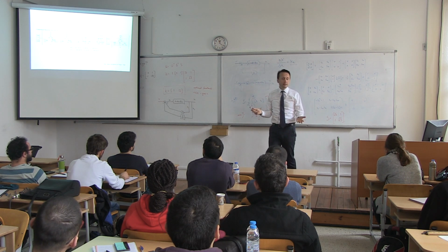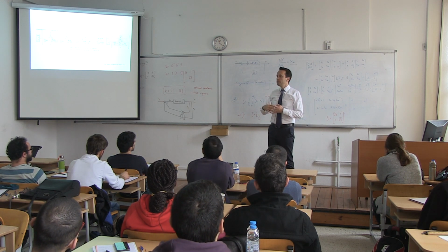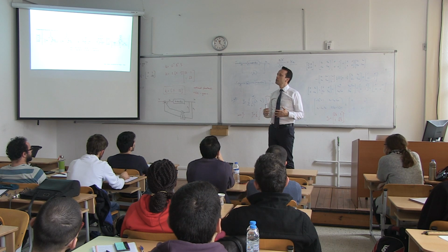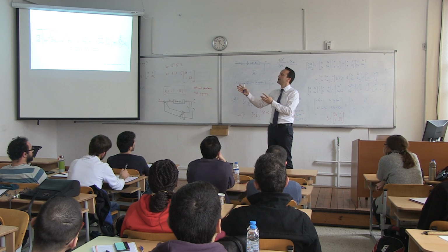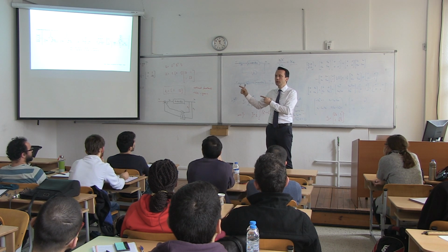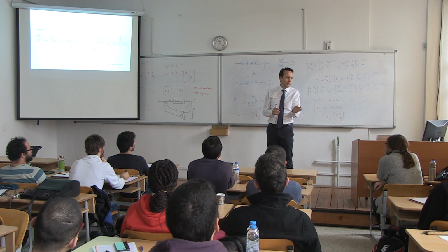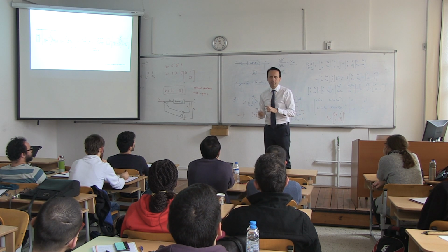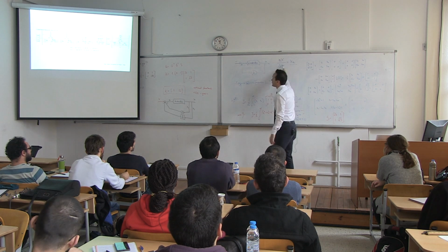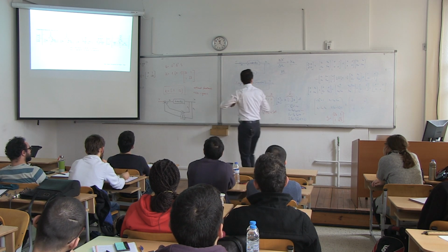Well, the way you calculate this, you do it through wind tunnel testing, or you do CFD analysis, or you do flight testing, or you just look at similar airplanes and say an airplane has this del x, del u, and my airplane looks awfully similar, so it must be similar, and you choose that number. Okay? And you use that. You look at the second one, it's del x, del w.